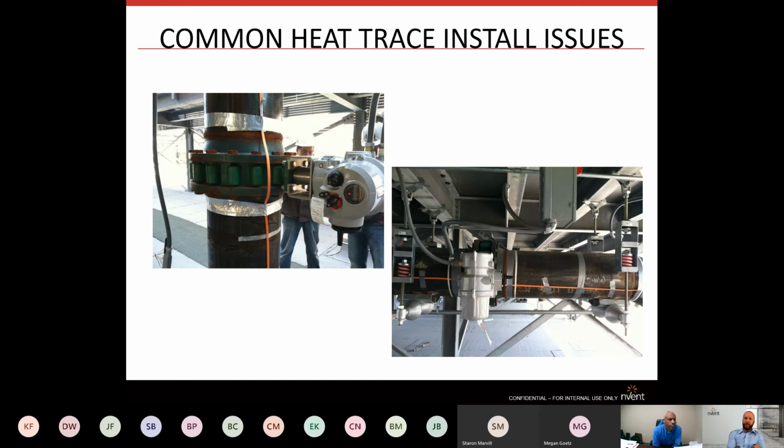So you can see here, we have a heat tracing cable, which is probably sized right for that straight run of pipe. But when you get to a valve, or that flanged valve right there, you need to apply additional cable. You need to do an additional loop wrap of that valve. You can see that there's more mass there at the flange and the valve. And also, when that pipe does get insulated, insulation is not going to cover this entire actuator right here. And the actuator is physically connected, metal on metal contact. So that's going to be pulling heat out of this larger portion into the actuator and dissipating it into the air. So you want to compensate for that additional heat sink by adding cable.